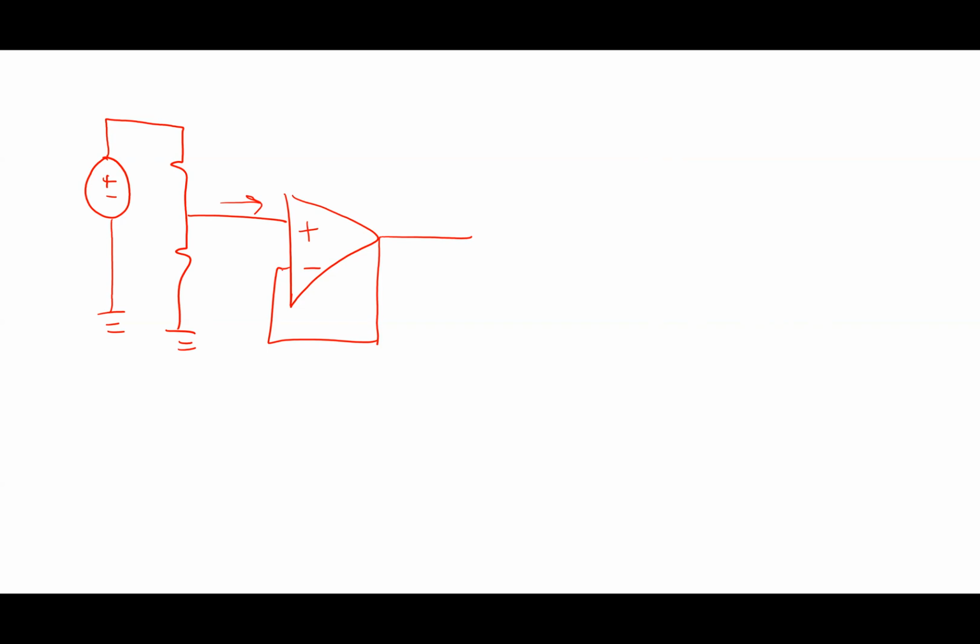V plus and V minus, what are they equal to here? The same thing, right? V plus and V minus are the same thing in this circuit, right? So which one can I tell? Yeah, so which one is R6 and which one's R7? All right. Okay. So what is V plus? Yeah, so this is 15. So this would become R6 over R6 plus R7 times 15 volts.